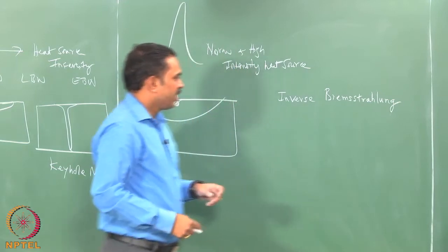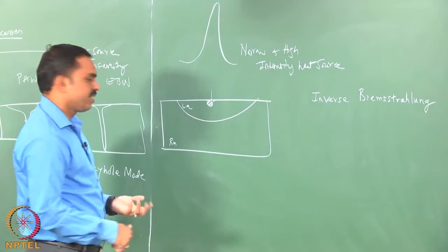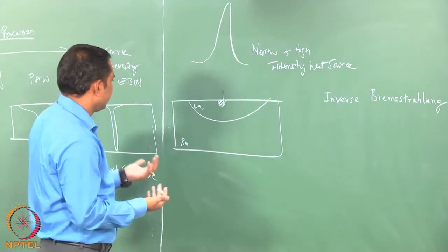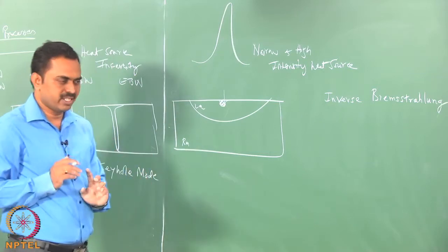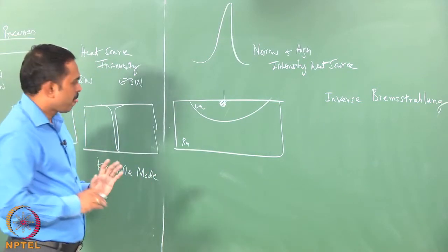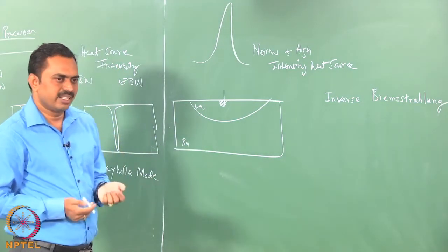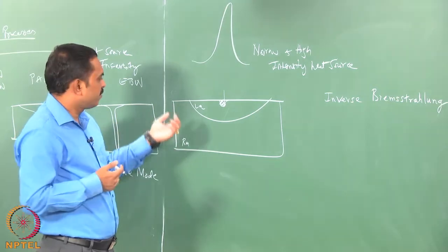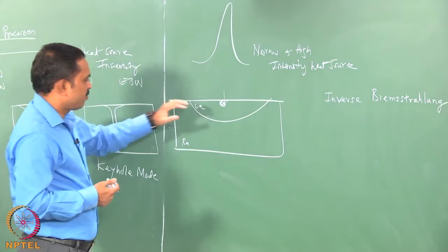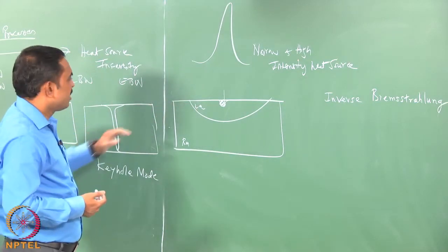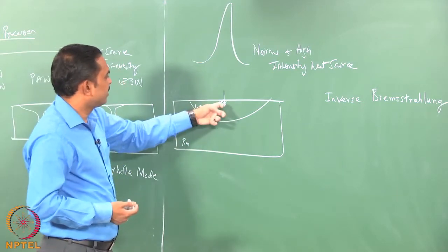This is basically a phenomenon in which the vapor is going to absorb the laser light completely, which is very different from the rest of the material, because as we discussed during the process overview, laser beam absorptivity in solids is less than 10%, and it reaches some reasonable number for liquid, but for vapor, because of inverse Bremsstrahlung, you have complete absorption of laser light happening in the vapor column, and that means enhanced heat is delivered to the beam.